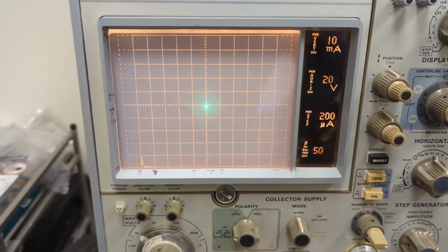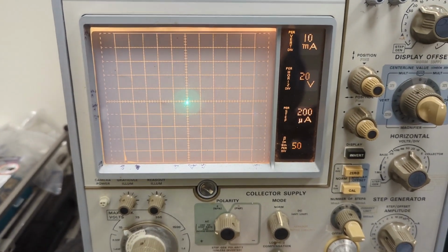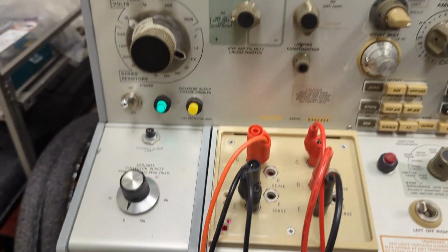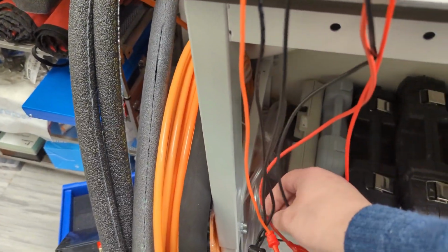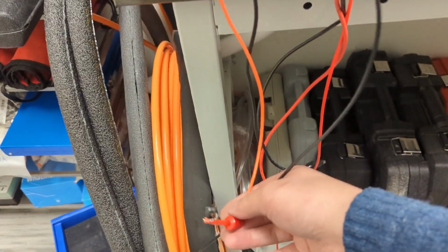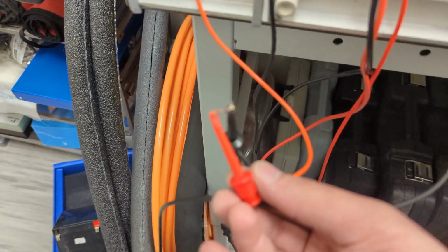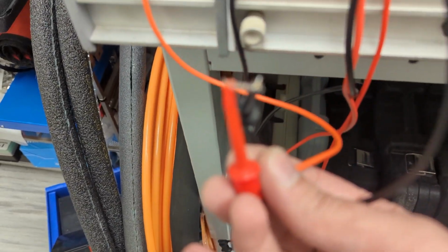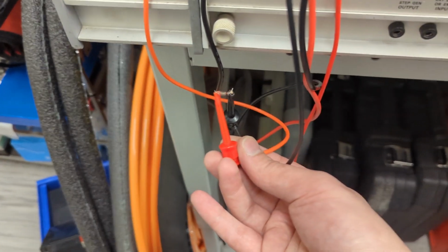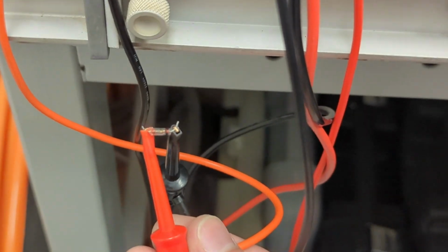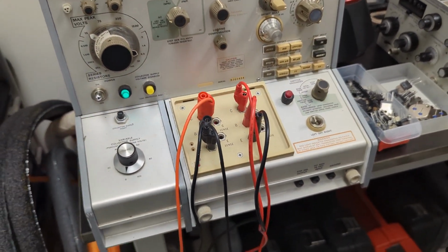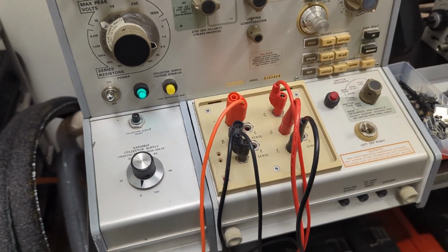Well, I think I might have found the problem. I should have had the video going when I initially fired this guy up. I shouldn't have shown you my precarious cables, but this is the 9 volt temperature compensated Zener diode, which is the reference for the 100-volt rail, which is the reference for all the other voltage rails. Sorry, my camera's not focusing.